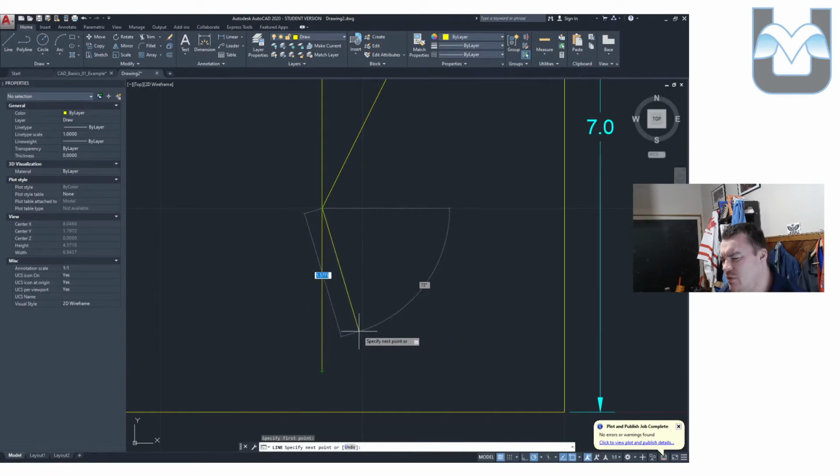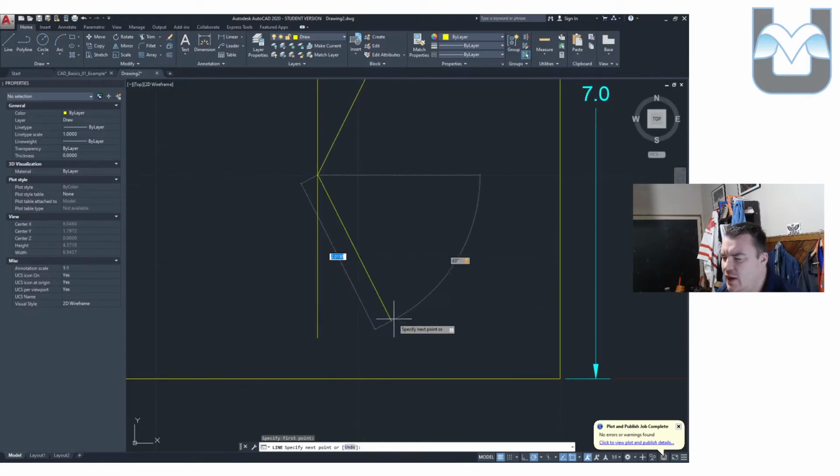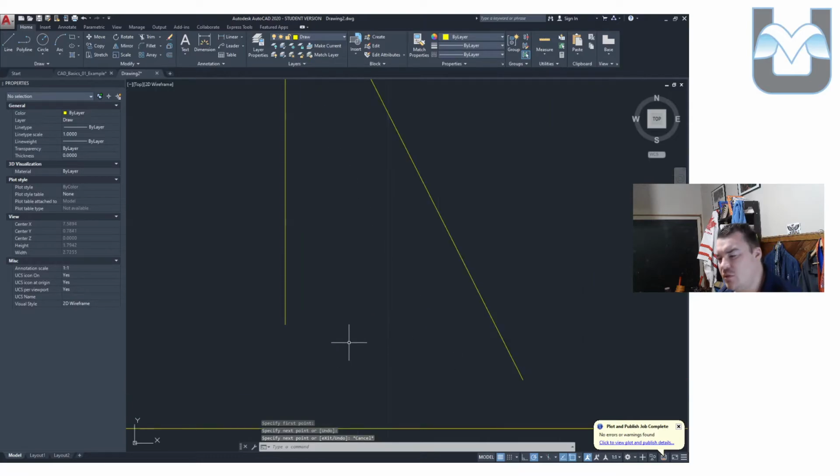But you'll notice that in your measurement, it measures from horizontal. It measures from 3 o'clock on the clock. So we actually have to do some math here when we do this one. So on this one, we end up getting 27. We end up getting 63 as our angle. That's 90 minus 27. And I'm just going to draw this line a little longer than I need it. Let me show you why in a second.